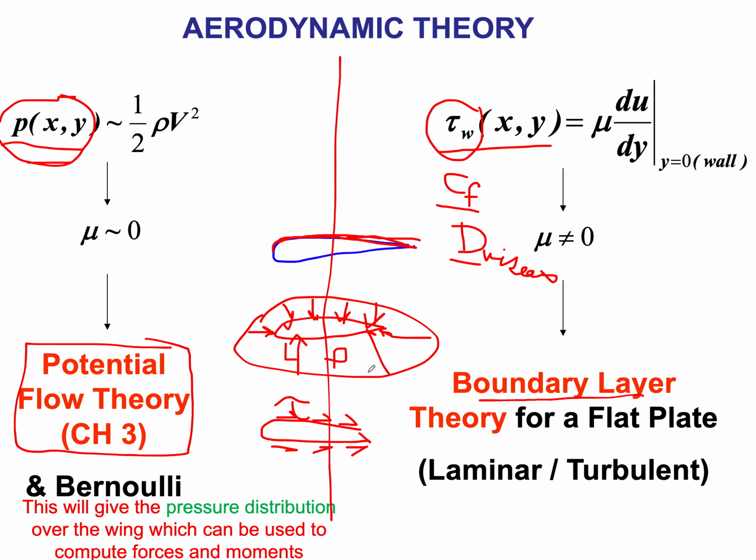From the irrotational flow, we defined the velocity potential function, which is only defined for irrotational flow. From the velocity potential, we can get the velocity distributions, and once I get the velocity distributions, I'm going to use Bernoulli to get back to the pressure. That's our game plan for this new chapter, which discusses the potential flow theory.